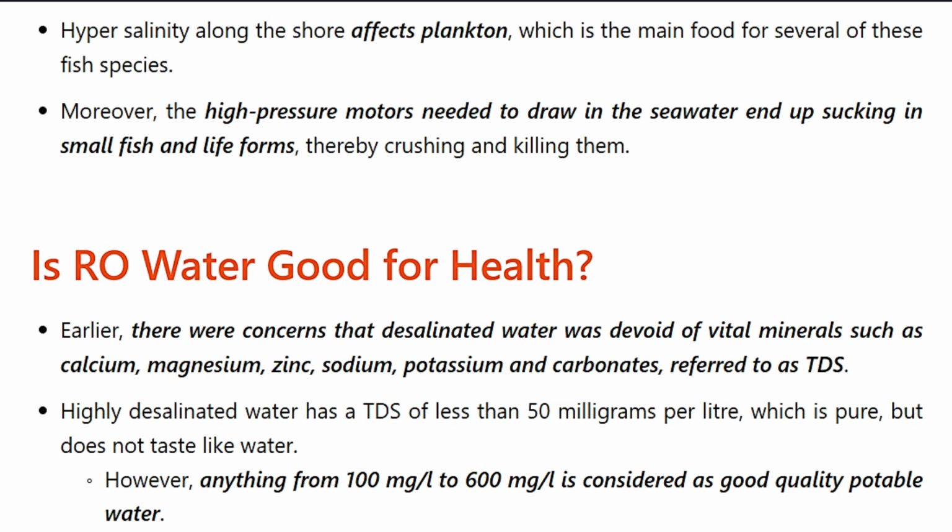Earlier, there were concerns that desalinated water was devoid of vital minerals such as calcium, magnesium, zinc, sodium, potassium, and carbonates, referred to as TDS. Highly desalinated water has a TDS of less than 50 mg per liter, which is pure, but does not taste like water. However, anything from 100 mg/L to 600 mg/L is considered as good quality potable water.